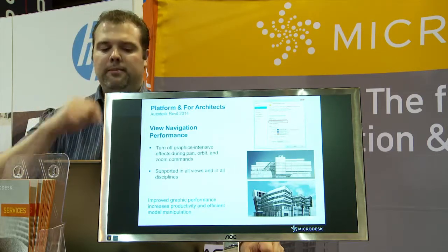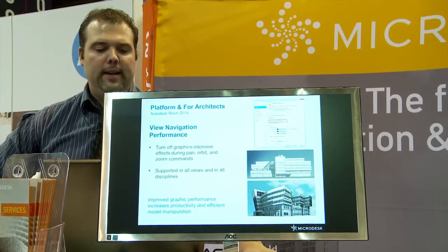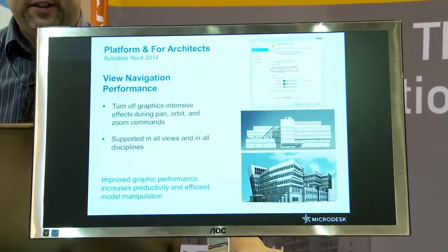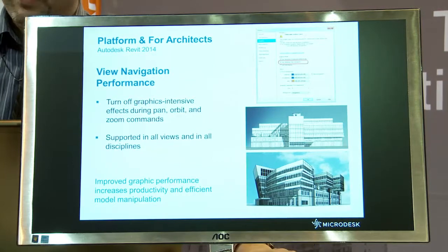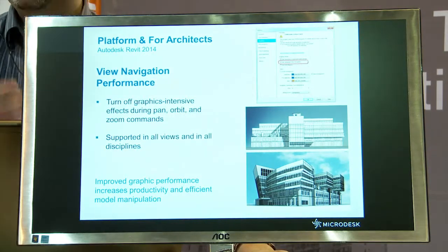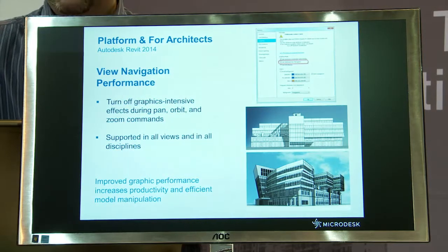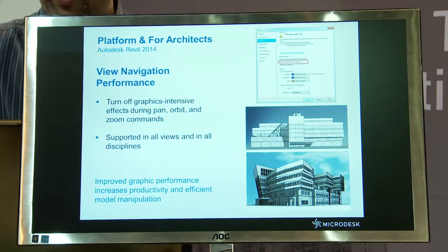And time related is performance. I can't count the number of people that say Revit is slow, there are not enough numbers. But it's not related to the program, it's sometimes related to graphics, to things that you're trying to do, and a lot of graphic-intense tasks. You can now control things in the option for graphics mode, where you now have something called optimized navigation.